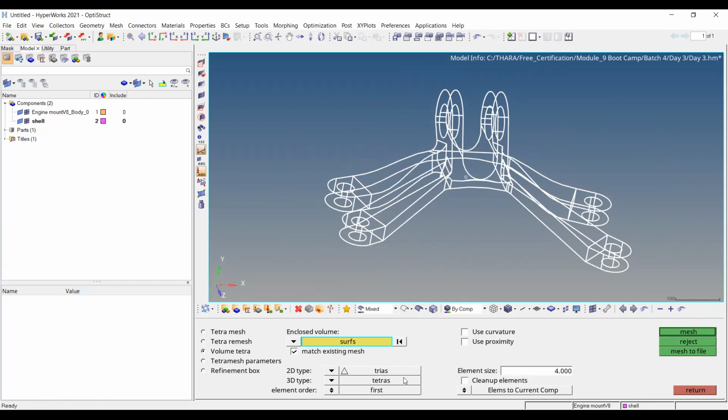But here one thing you need to observe. Here I have given an element size of 4 mm. In module 2, in the F12 panel, we defined some number, that is the element size. According to our element size only, the elements will get created. So the element size matters more, because this is a major and important parameter that we are going to define. Based on this number only, the complete component's elements are going to be created.